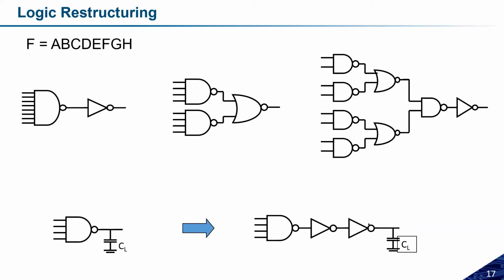Because the single unit inverter will have less delay, after inserting the buffer, the loading effect, the self-loading effect I was talking about, can be overcome. So this could be another alternative. Why are we using this buffer? It does not affect the functionality of the circuit I have, but after inserting it, it isolates the fan-in and fan-out.